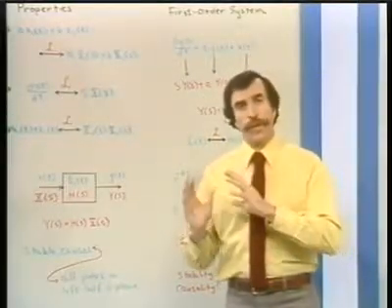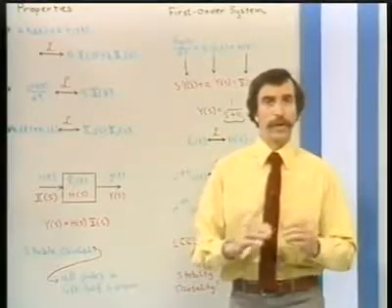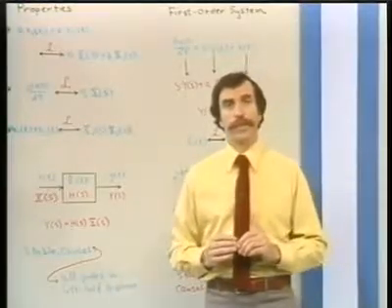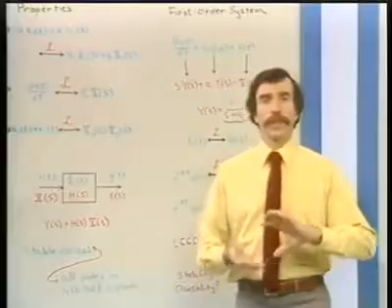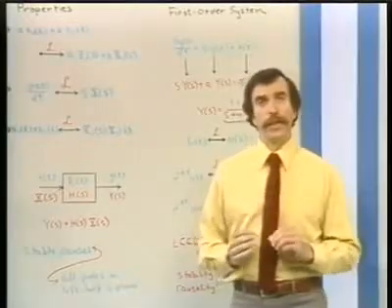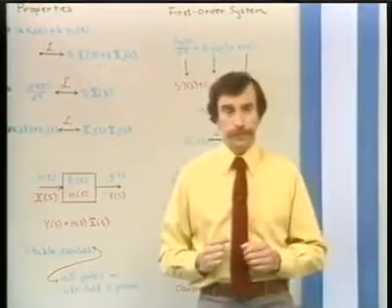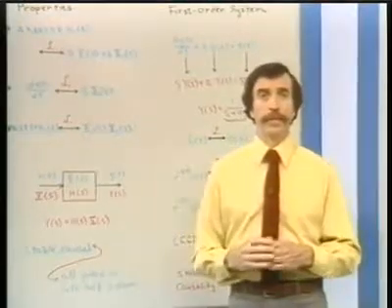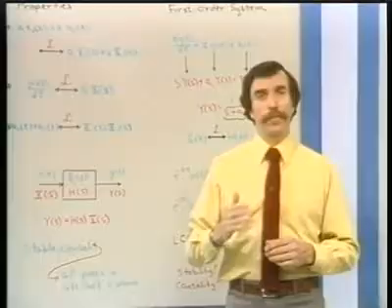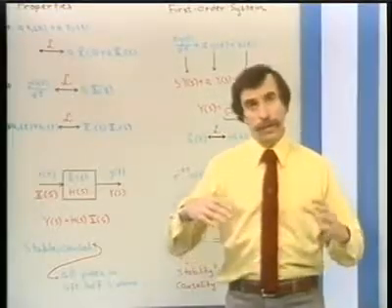some issues of the region of convergence, and for that matter, location of poles of the system function, are closely tied in and related to issues of whether the system is stable and causal. And in fact, there are some useful statements that can be made that play an important role throughout the further discussion.